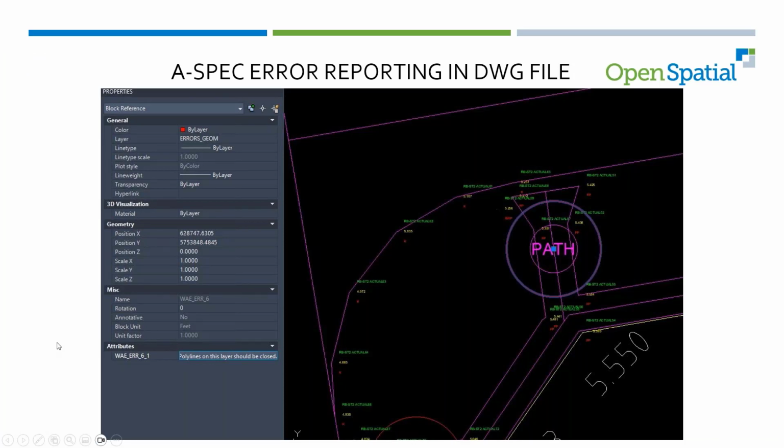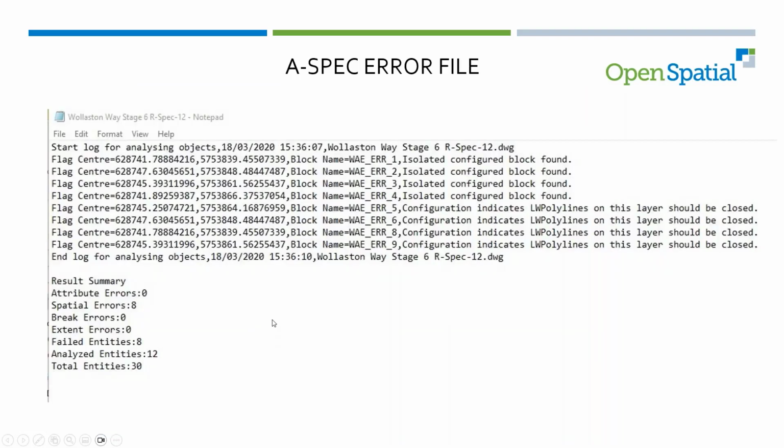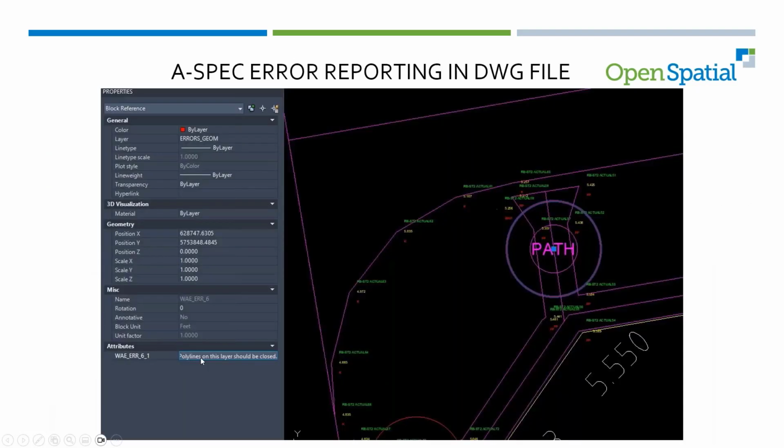One of the things with ACDC is all of this error checking. So if your drawing does not pass, then you're going to get a failed drawing, which you can download, and it will have circles in it with markers. And that little comment down at the bottom there shows what's wrong. And so this is saying, look, that's an RSpec roadway area and it needs to be a closed polygon. So we're checking that one.